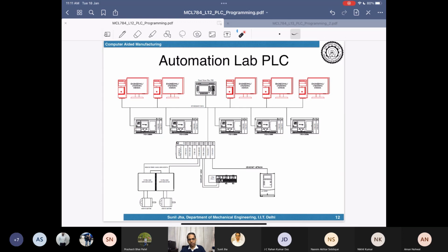Last time we have seen that whenever we have to connect a pressure sensor, we are looking forward to interfacing with the current output over a large distance. But in this case, even the distance is much higher. If it is 100 meter or 150 meter, you can use these remote IOs. So these are the remote IOs.